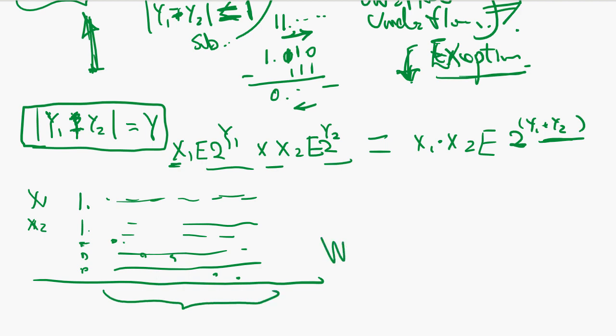And this is again a Wallace tree, and the Wallace tree using ternary logic is going to shorten the tree length by a quarter, because each adder has one additional input.